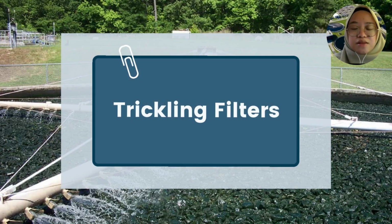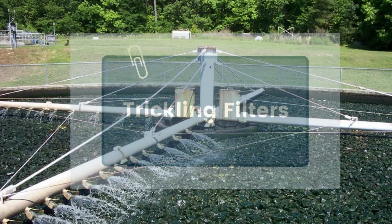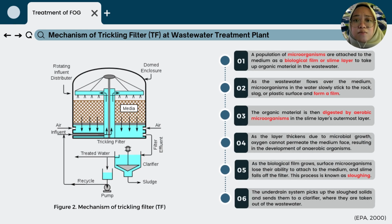The second treatment that can be used to remove fat, oil, and grease is trickling filters. Here is the mechanism of trickling filter at a wastewater treatment plant. Firstly, a population of microorganisms is attached to the medium as a biological film or slime layer to take up organic materials in the wastewater.